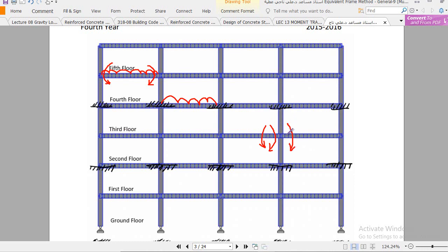So for each span you find out the direction of the moment, and finally you have to extract this joint, right here, and show all those moments which are acting over that joint, and find out the net moment over this joint, because some moments will cancel out each other's effect. Like you see here, this one, let's say this is 10 kip-feet moment, and this is, let's say, 9 kip-feet moment, so the net effect will be anti-clockwise due to this moment.